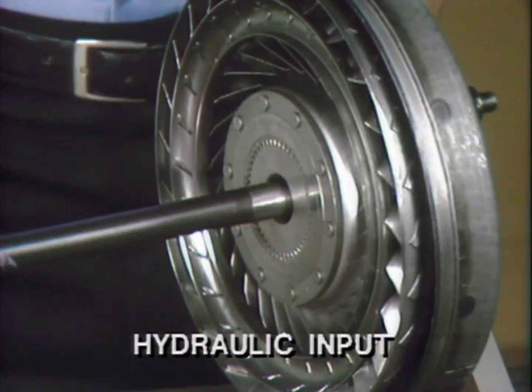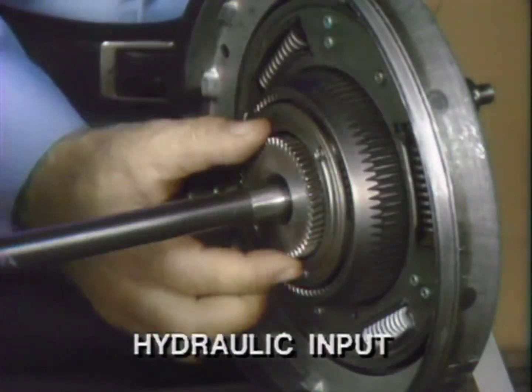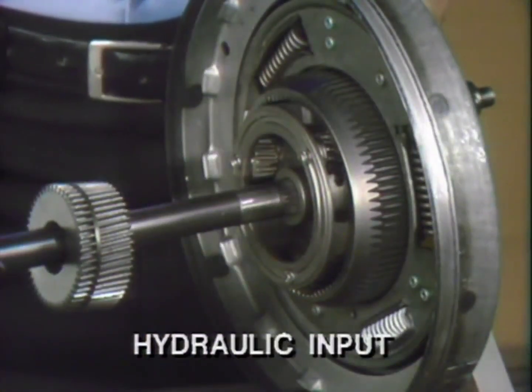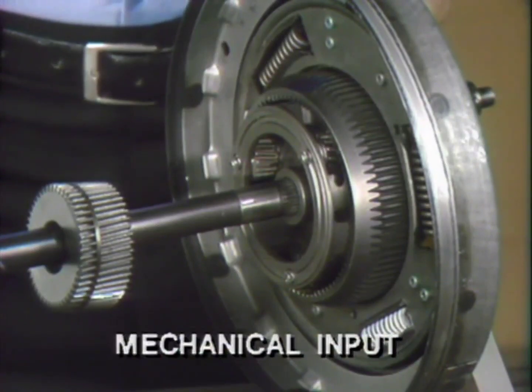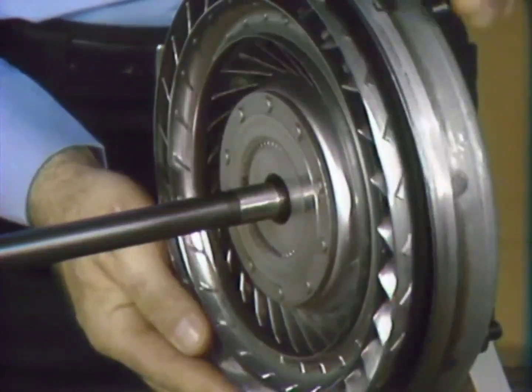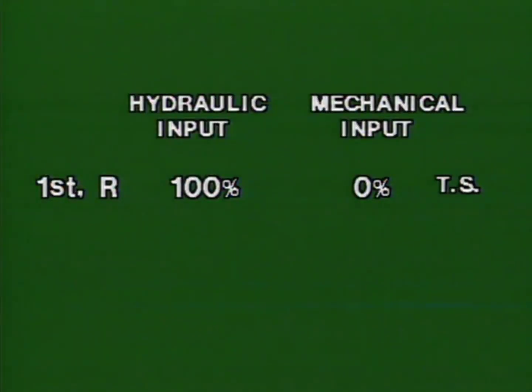Now the hydraulic input goes the other way, from the turbine to the sun gear, to the planet pinions, to the pinion carrier, to the intermediate shaft, and into the main gear train. At the same time, the mechanical input is through the cover, damper, ring gear, pinions, planet carrier, and intermediate shaft, as we saw earlier. The splitter planetary unit combines the mechanical and hydraulic into a single split torque input through the intermediate shaft. This chart shows the input drive percentages in each gear.